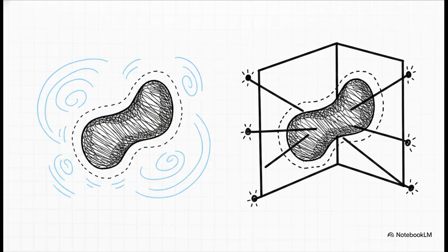All right, here's the big aha moment. Without datums, your profile tolerance is controlling the form, and potentially the size only. Basically, the shape of the part has to be correct, but that tolerance zone can float freely around in space. It's not tied down. But the second you add datums to the feature control frame, you lock that tolerance tube into a specific datum reference frame. You completely constrain its translational and rotational degrees of freedom. So now, not only does the shape have to be perfect, but it has to be perfectly located and perfectly oriented relative to your specified datums.